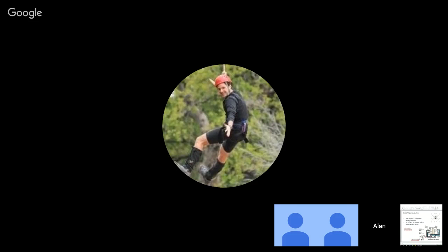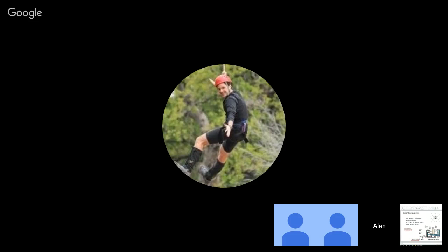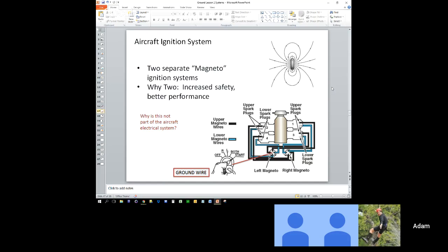So does the alternator kick off the cyclical system, or when you hand start a prop? I think what you meant when you said alternator was starter. Yeah, thank you. I was thinking starter. So exactly right. That's the reason you can hand prop an aircraft and start it. You can actually create that mechanical rotation inside the magneto by turning the engine, and thus jump a spark in one of the cylinders. And if you do it just right, you'll actually start the engine with the prop.